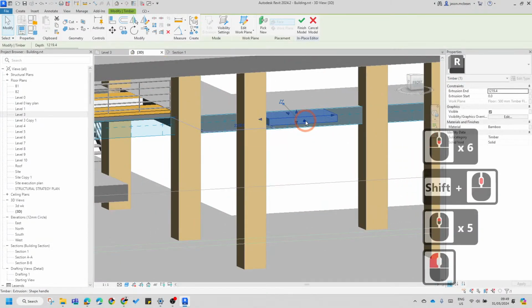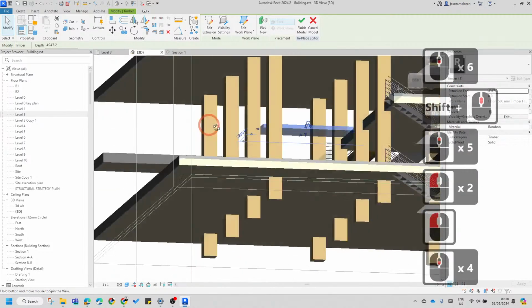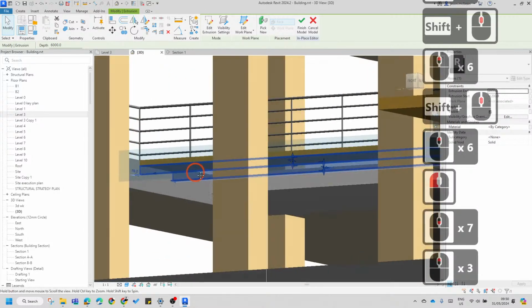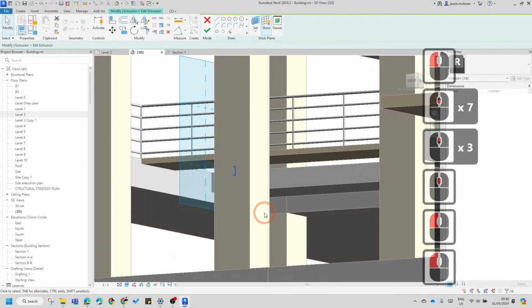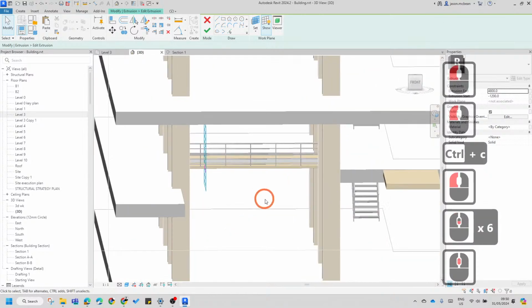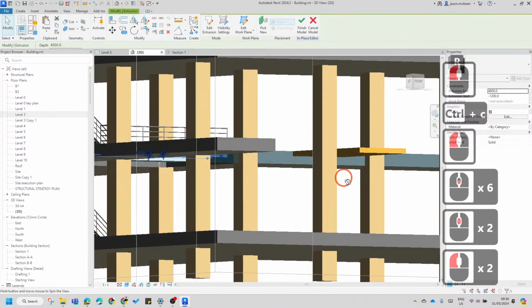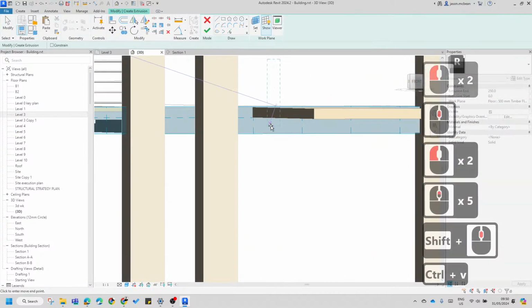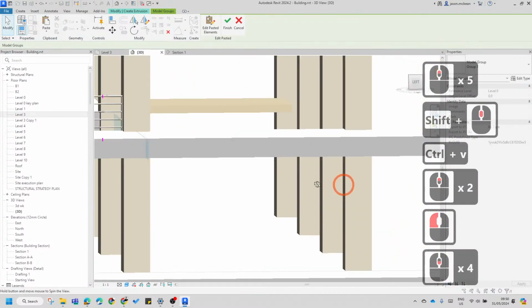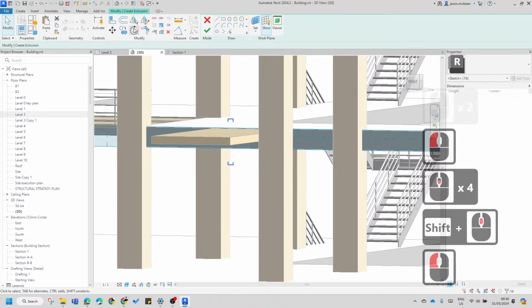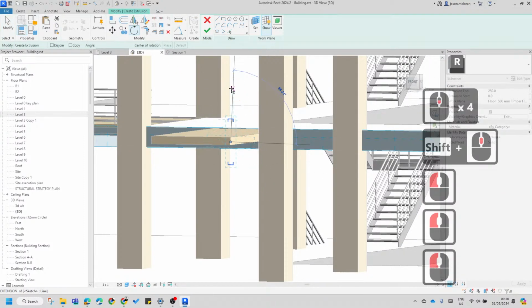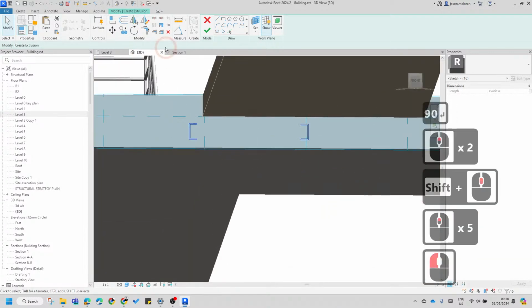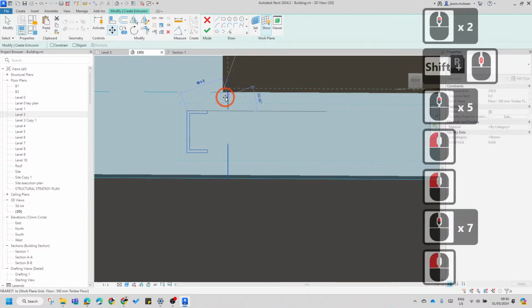Now this guy I can now extrude. I can copy these. What I like about this, watch this. This is what's cool. I'm going to go and edit extrusion. Control C. Copying those shapes. Finish. Now watch this. Create extrusion. New work plane. Control V. It does get a bit whack sometimes because it doesn't know, but you just rotate. Now I just move them into the right place. See what I did there? I copied that exact shape.